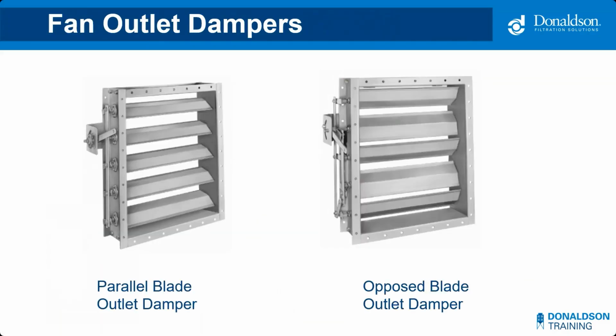If you spec a system without a VFD, the fan should have at least a mechanical damper so the operator can manually control airflow. They generally have a lever that the operator moves to open and close the damper as needed. For example, immediately following a filter changeout, when the pressure drop is low and the flow is high, the damper should be closed to a point that it maintains proper airflow.